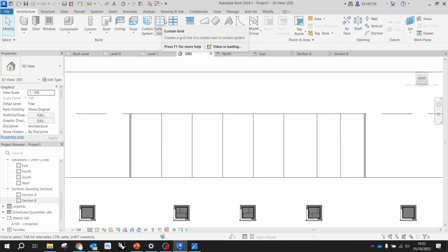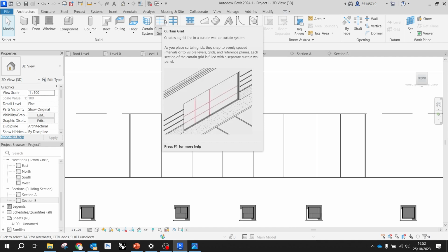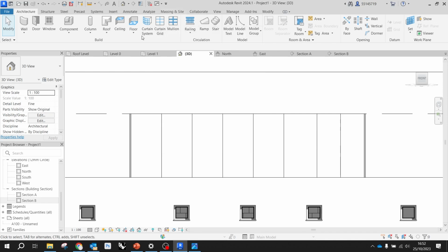by using annotations. And I want to show you that annotations in Revit are more of a live thing. Is there anyone here who already used annotations, say in AutoCAD, for instance? You've been using annotations in AutoCAD, right? In Revit, when you assign annotation to distances, those things become live and they become attached to the annotation, same way as the levels did previously, right? So if I change numbers on the annotation, also the positions of geometries will change. I'll show you exactly what I mean.